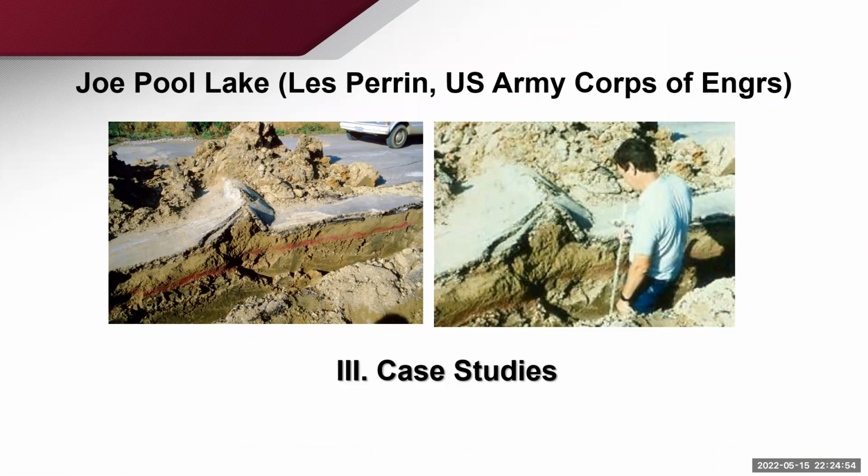That's another major problem. If you go and sample, you can very easily miss the location where sulfate is present. So you need a lot more sampling of the soil at different locations, and then you can see where this problem is happening. You can't just do 2 or 3 samplings; testing for sulfates that way is not sufficient to understand this heaving.